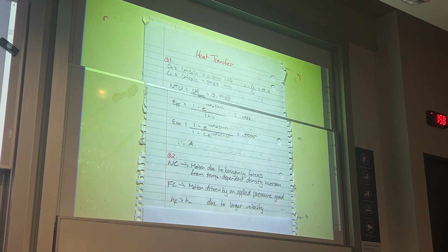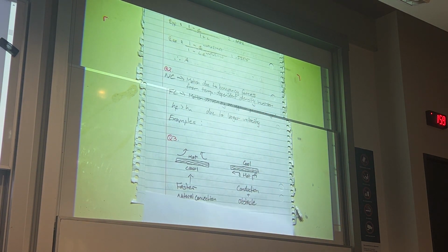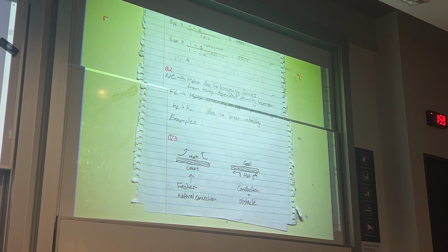If you sit the plate with hot side down on this table, it's probably not going to conduct heat through it as well as the air would. And the table's going to get really hot underneath the plate. We know heat transfer is driven by a temperature differential, so you're going to decrease heat transfer. If you sit it up, we're going to get faster heat transfer initially because we're going to get convection instead of conduction. And because we have air circulating, we usually get air that's always at a much lower temperature than what the table would be. So I asked you to draw a diagram as well. The diagrams you're expected to draw are something along the lines of this.